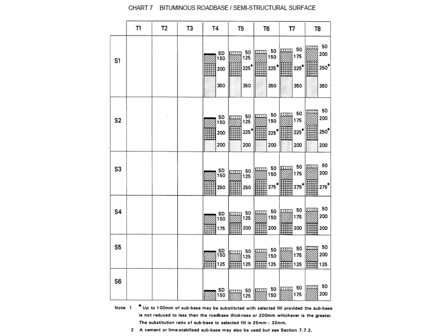While we were discussing the footnote, if I look at the footnote again, a very important point is that up to 100 millimeter of subbase may be substituted with selected fill, provided the subbase is not reduced to less than road base thickness or 200 millimeter. So this note should also be considered, because on some charts we have this note, so this option can be exercised.